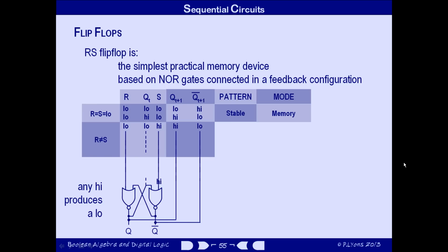But remember that any time that an output changes, your analysis hasn't finished, and you need to keep on tracing the voltages around the circuit until they've settled down. Fortunately for us, the circuit never goes into oscillation. The outputs do always settle down, after reanalyzing one gate, sometimes after reanalyzing both gates. So since this same principle is at work for each row of the transition table, we won't bother to talk through the details of the remaining rows. It won't do you any harm, though, to work through it as an exercise to assure yourself that you can predict the values in the rest of the table.